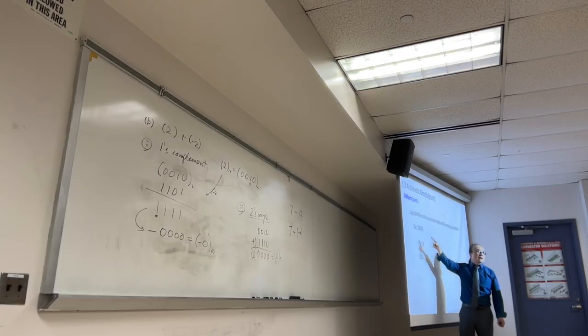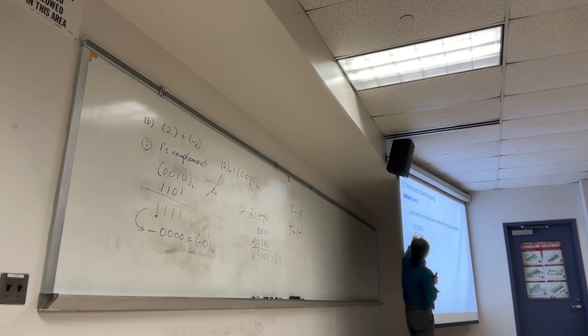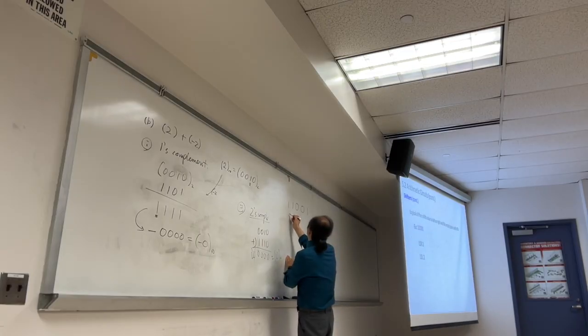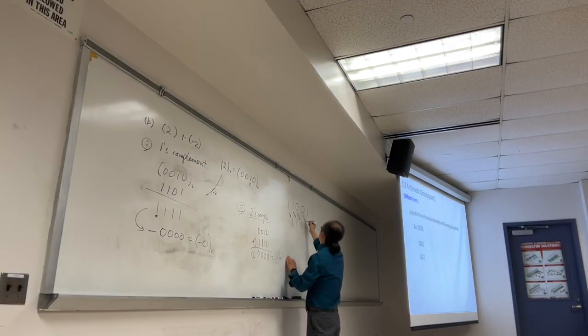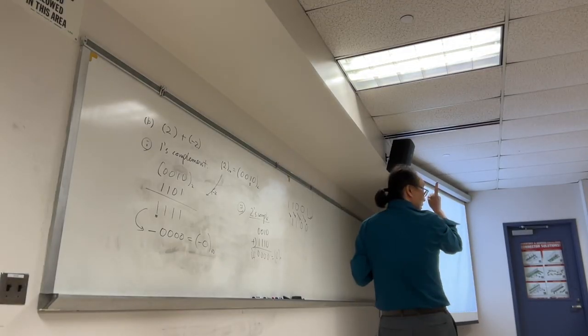You will be given any binary number in the register. All of this ARM architecture for our version is going to be 32-bit. For example, we have 5 bits. You're given 11001, and we want to logically shift to the right by 2. What's going to happen? Shift to the right by 1: 1, 1, 0, 0. This guy is going to go away. This is the logical shift to the right by 1.